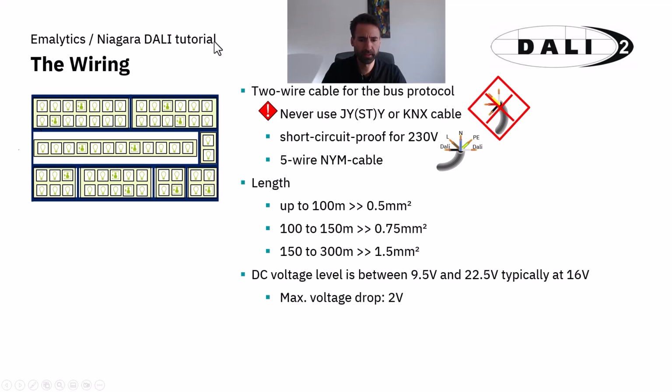On the DALI bus we have a DC voltage level between 9.5 and 22.5 volts, but typically 16 volts DC. And the maximum voltage drop over the whole cable length should not exceed 2 volts.